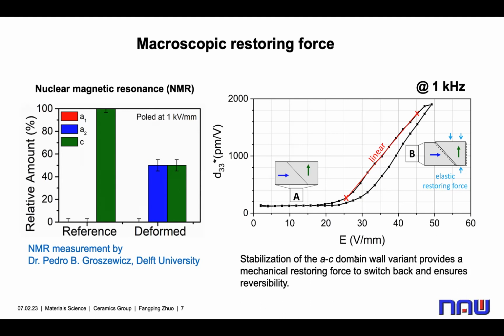In this case, the microscopic restoring force will ensure the reversibility of the d33*. So based on this work, by using the mechanical dislocation imprint, we can basically control the polarization and the domain structures and enhance the piezo response.